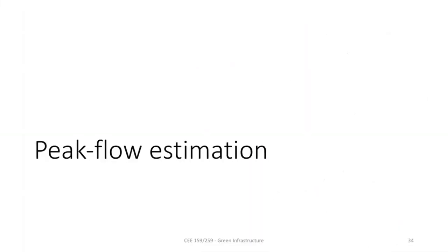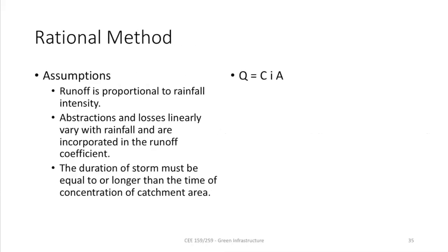for your project. So the question now is why we need all this for your design project, because you want to know what the peak flow is. Imagine if your rainfall happens longer than the time of concentration, that means you are going to get the very high flow rate. Once the rainfall lasts more than the time of concentration, the flow rate will not change anymore, because every drop that dropped there has also already exited the system. It's not concentrating anymore. So that's just the reason why we use it.